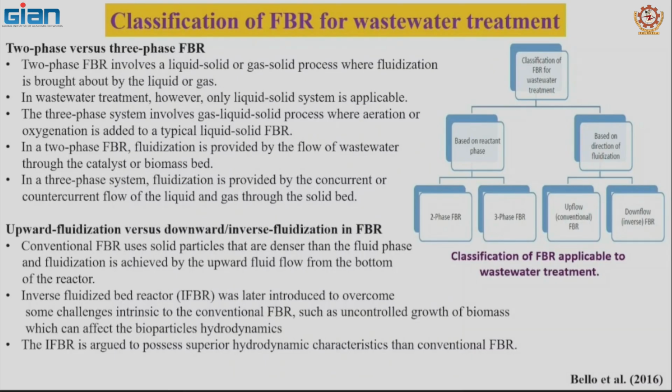This is a characteristic and a disadvantage of the conventional fluidized bed reactor, and can be avoided using the inverse fluidized bed bioreactor. In an inverse fluidized bed bioreactor, solid particles lighter than the liquid phase are used. The inverse fluidized bed reactor is argued to possess superior hydrodynamic characteristics than the conventional fluidized bed bioreactor.